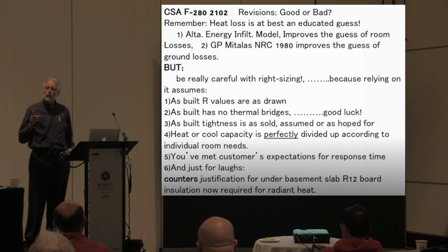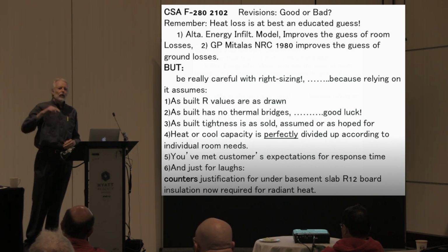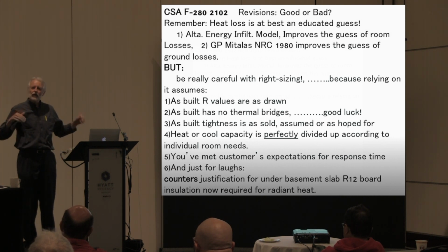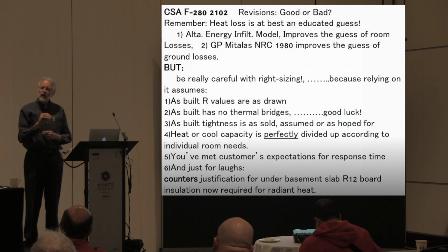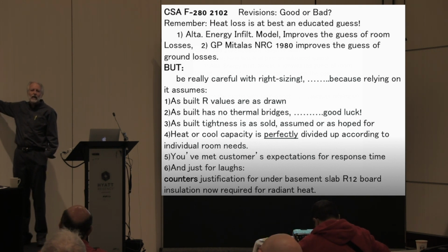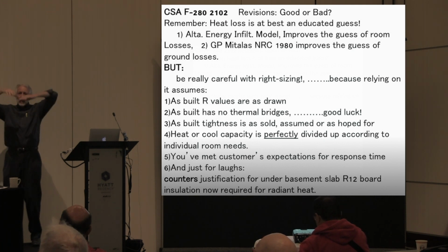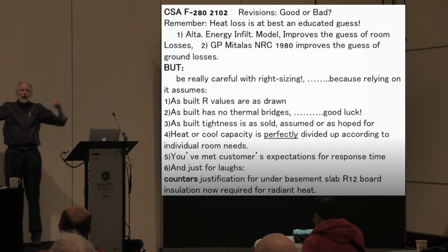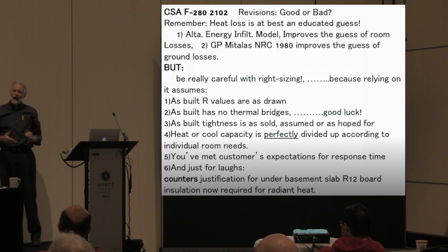You guys being here probably have already had enough building science information to know that in the wintertime, the stratification that we always talk about, and the discomfort that it brings in the basement, is not what we call a static event. It's a dynamic event, which means your furnace runs to keep the thermostat at 72 degrees, 5 feet off the floor on the main level. This furnace does not know what's going on in the basement or upstairs, because there's ongoing infiltration at the basement, rising of warm air, and exfiltration at the top. The result is a dynamic event, and the strength of that change is driven directly by the height of the house and how cold it is outside.